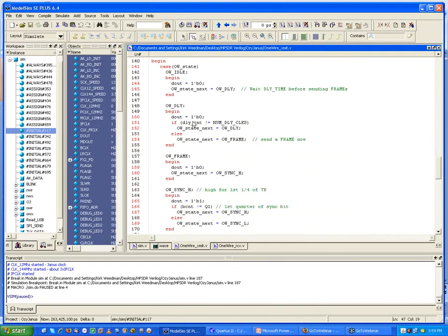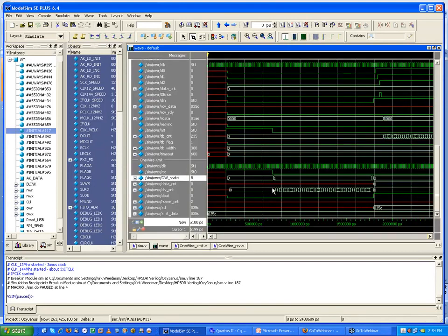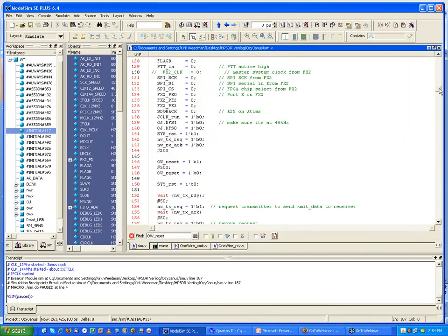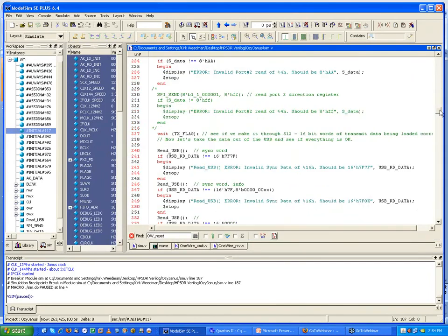So then in the delay one, in state 1, we stay in that state as long as this delay count hasn't reached this value. Okay? Well, delay count on reset also gets cleared, and then it just starts counting. Okay? So that's what we see going on right here. So after the reset goes away, it starts counting up. And so it gets to a value up here of 50. And how did it get to 50? Normally it's a lot longer, but in simulation, I overrode that value in my instantiation.